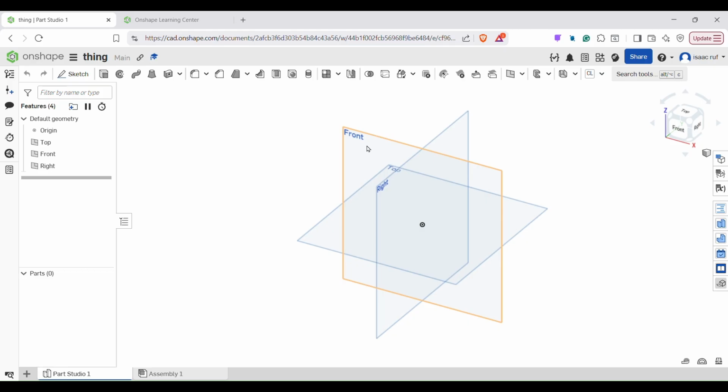What parametric means is it comes with the word parameter, and that means you can put in different parameters and the design will auto update. So that's our goal for most designs, is that we can change the parameters of the CAD without seriously breaking the CAD. In practice, this isn't always possible. Especially with complex geometry, updating dimensions can be tricky. And if you're not making production parts, it's not a huge deal for what we're doing. A lot of the parts we don't have to change that much, and we can mess with them a little bit. But for the most part, our goal is to make parametric designs.